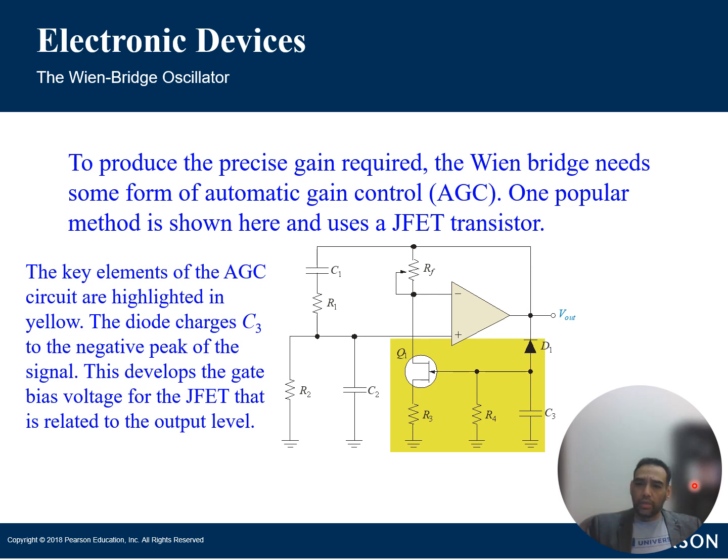And then the oscillator's frequency is given by that standard formula of 1/2 pi RC, right? Which I don't have it here. Yeah, frequency is equal to 1/2 pi RC, right? Yeah, I'm sure it is. So you adjust either the resistor or the capacitor values, and then you can tune the oscillator to the desired frequency. Now let's go to the amplifier stage.